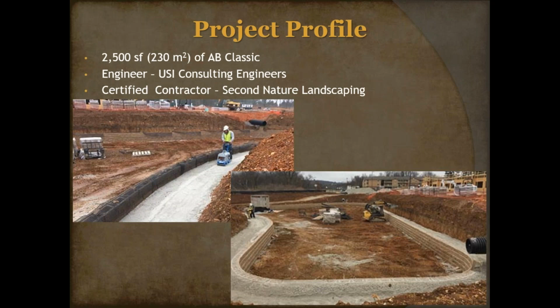But what was interesting, I mentioned that they had to design the wall with a couple different design phases in mind when it comes to water management. So the first 5 courses, you can see being constructed here. Compaction was really tight because they wanted to minimize the differential settlement potential, because we know water will move things around. So they really concentrated on consolidating the rock. You can see you almost have 5 courses of block going all the way around, and that gives them the capacity they were looking for for a certain percentage of that rainfall.